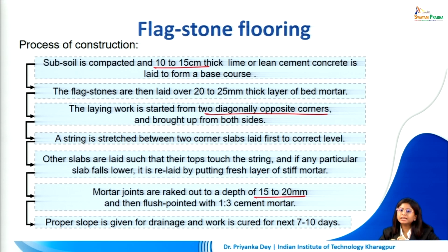So, the basic idea is a certain amount of mortar from the gaps between the flagstones will be scooped out in a particular shape to ensure that it is well stable and no excess mortar is actually bulging out, to maintain a flush surface. So, different ways or patterns in which we scoop out this mortar is going to give different names to the type of pointing. We will of course discuss this, as I mentioned, further in detail in a subsequent module.